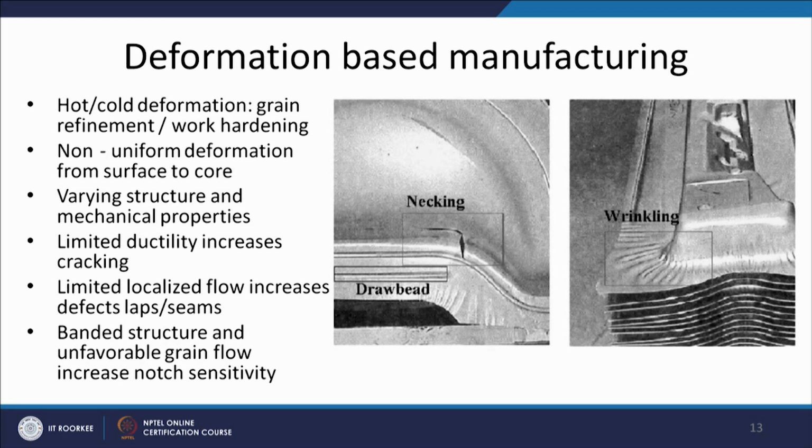Similarly, the surface layers in the component are subjected to greater deformation as compared to the inner portion, and that in turn also leads to a lot of variation in mechanical properties. Apart from this, cold deformation especially decreases the ductility, which in turn increases the cracking tendency.